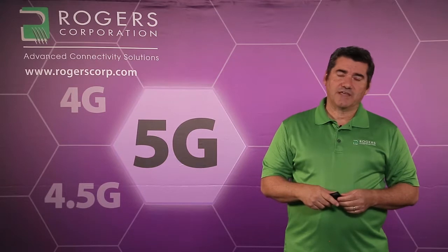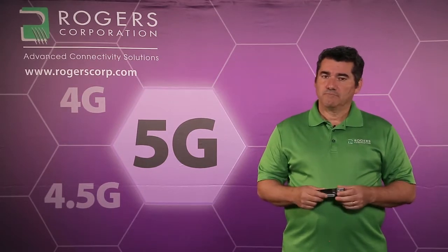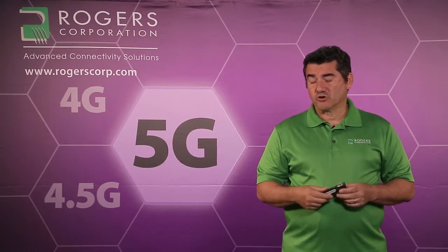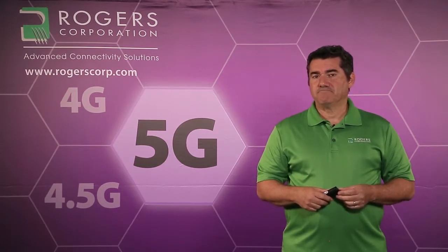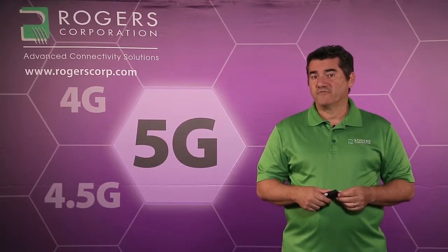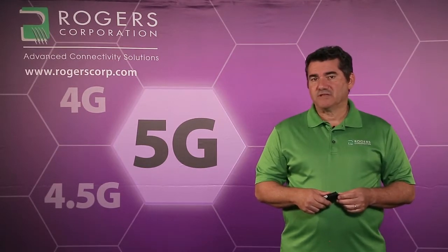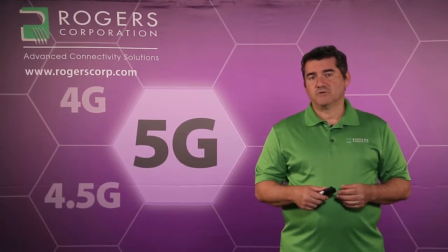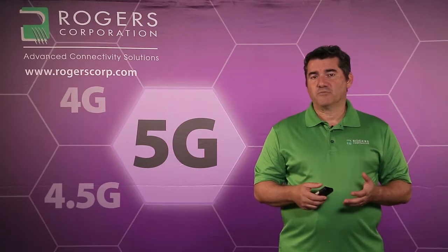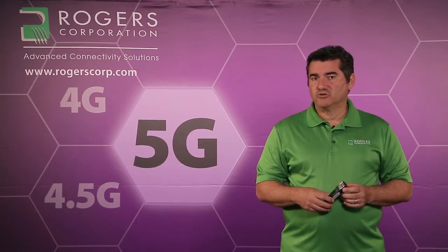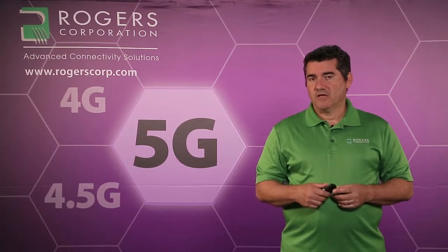In addition, designers have the option to work with metal plates to take away the heat. PCB circuit boards typically have thermal conductivity values in the area of 0.5 to 1.5. This is not enough to drive the heat directly off of the device. So what you want to do is adhere the circuit board onto a metal plate, either directly from the suppliers, or sometimes you use adhesive systems to do so. Rogers has a material that can do that.